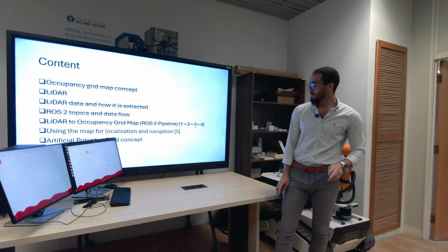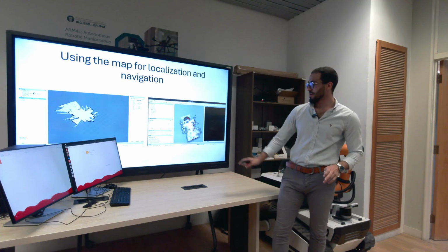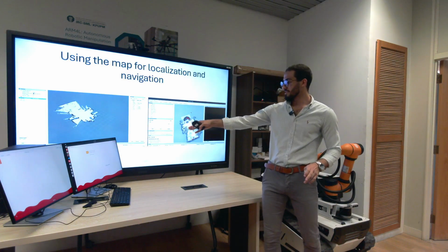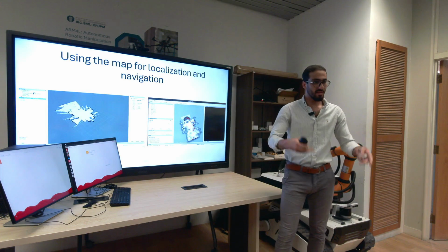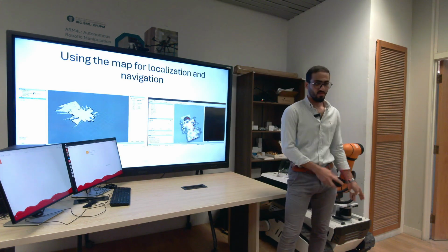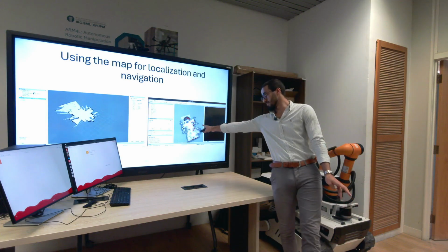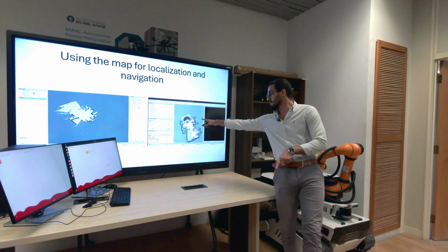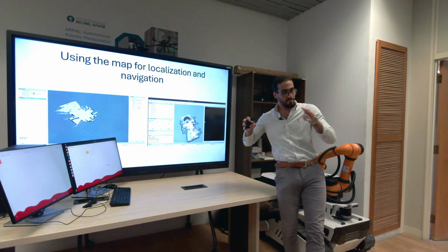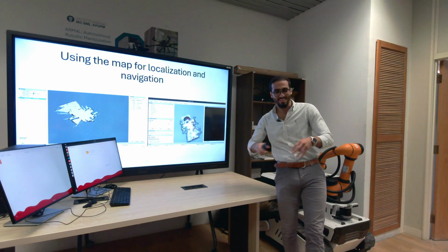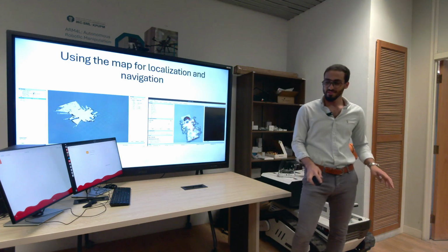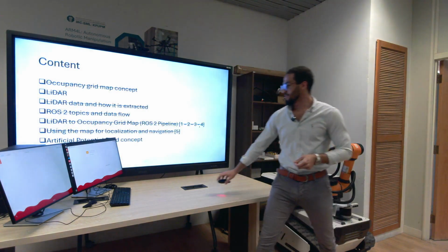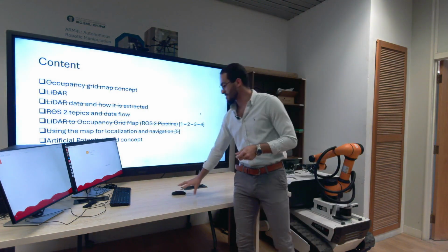Then in the fifth step, the navigation. So now we have navigation, put it on RViz. Then we have a live update from the LiDAR itself. The LiDAR will detect the wall, shown as these red dots, and if it matches the map, let's keep this for the experiment. It will be clear. Okay, so I think we can go now to the experiment.